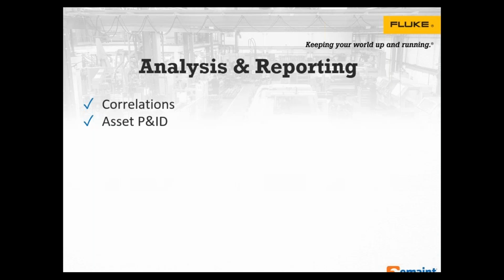This is where it's important to understand the piping and instrumentation diagrams, the P&ID, and any asset diagrams. Earlier we discussed understanding what's upstream and downstream of that asset, things that can affect that asset's performance. Sometimes it's good to get out there and understand the entire system, which seems obvious, but it's surprising how many times other components of the system aren't really looked into. Sometimes it's worth going beyond the asset to understand what the upstream and downstream effects can be. This is really a big one in many cases.